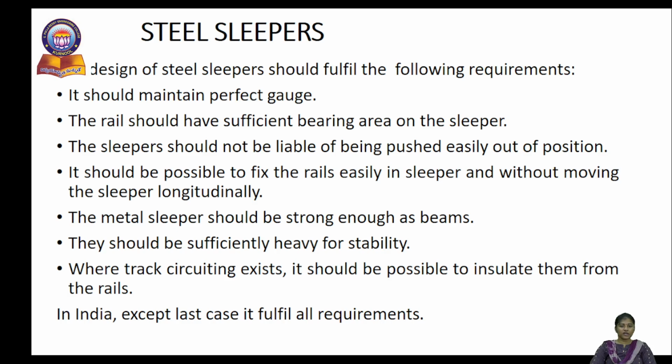The metal sleeper should be strong enough as a beam. They should be sufficiently heavy for stability. Where track circuiting exists, it should be possible to insulate them from the rails. In India, except the last case, it fulfills all the requirements.